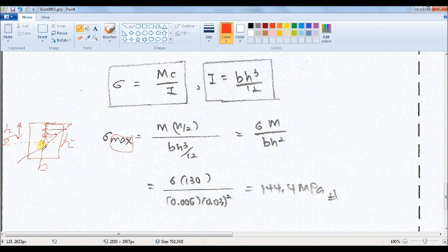That means at the center we have bending stress equal to 0, and here we have maximum tension, and here we have maximum compression stress. In these two locations, at the maximum distance, we have maximum tension and compression stress. Depending on the type of bending and the direction of the moment, on one side we have maximum tension, and on the other side we have maximum compression.